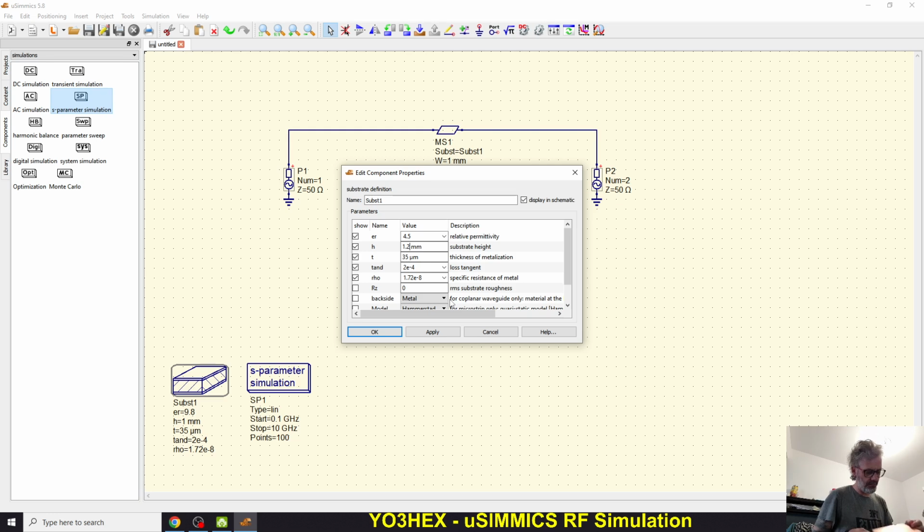Yeah. So you have only one side PCB, one side copper clad, and this is some copper foil. That particular PCB is 1.2 millimeter, and the copper foil that I'm using is 60 microns. Yes, it was measured. So yeah, you can go out and say, okay, the backside will not be metal, but it will be air.